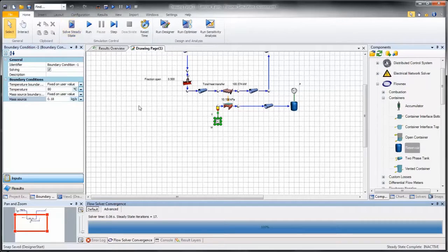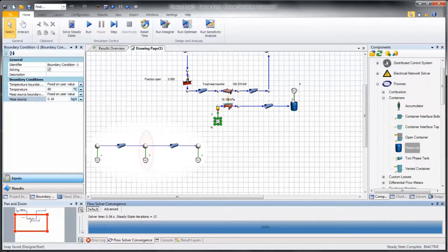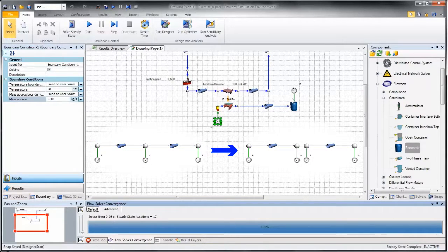Now I'm going to continue with the rest of the system, but keep the pressure boundary value specified on my reservoir. As we discussed in session 3, a pressure boundary in the middle of my network will isolate the sections on either side, which will analytically be similar to having 2 separate sections.